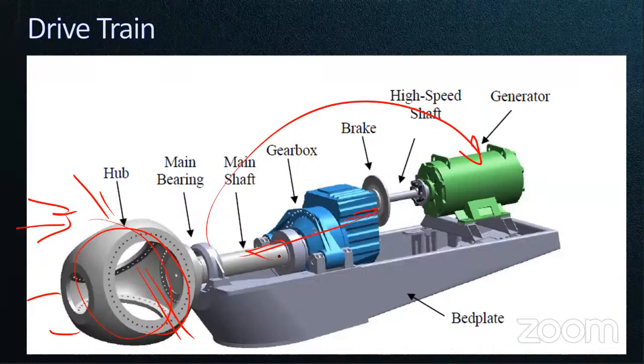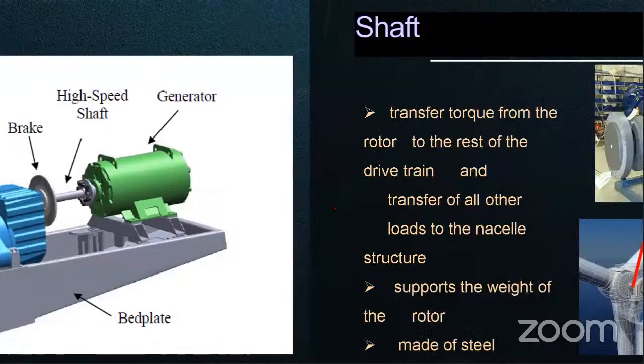called the drivetrain, right? So I have told you here we have the turbine. It extracts energy from the wind and should start rotating. This rotary motion has to be transmitted to the generator via the mechanical drivetrain. So this is called the mechanical drivetrain. It consists of the shaft, the low speed shaft and high speed shaft, then the gearbox, right? These are the mechanical components.